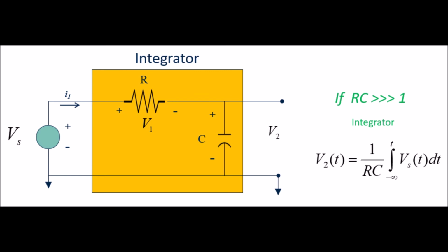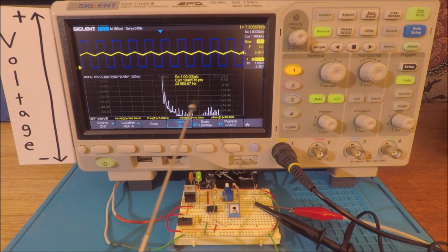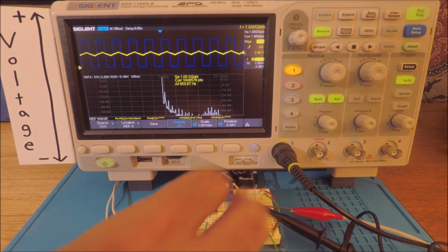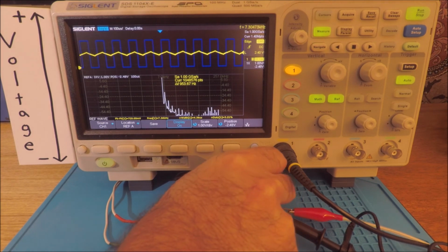Likewise, in the frequency domain, we can see that the harmonics have been even further suppressed because of the increased filtering. Of course, if we'd like to boost this integrated output signal up, we could add something like an operational amplifier, an op-amp, with some gain associated with it. Okay, let's restore our square wave by removing that capacitor.